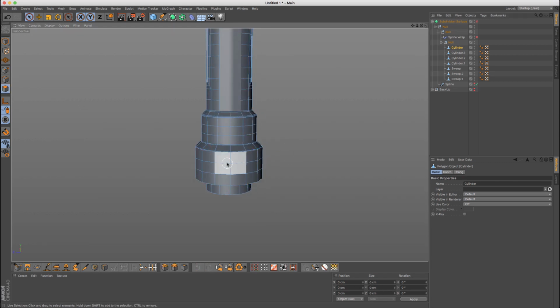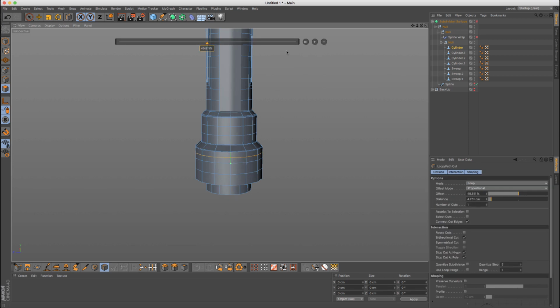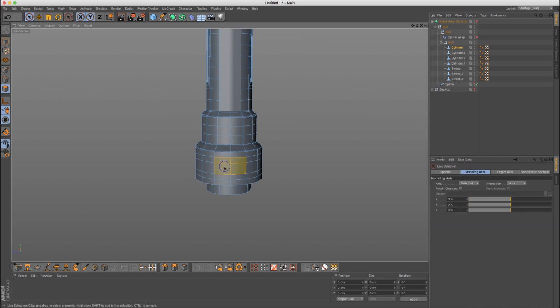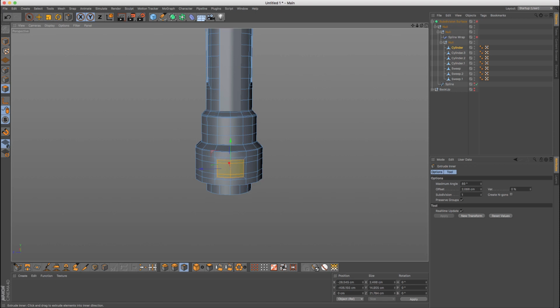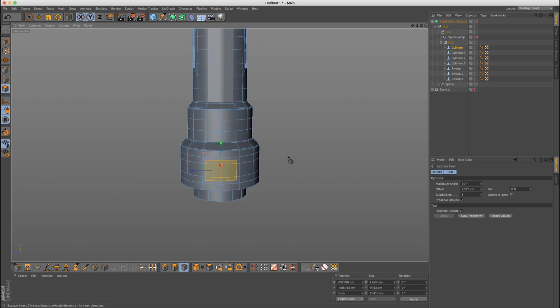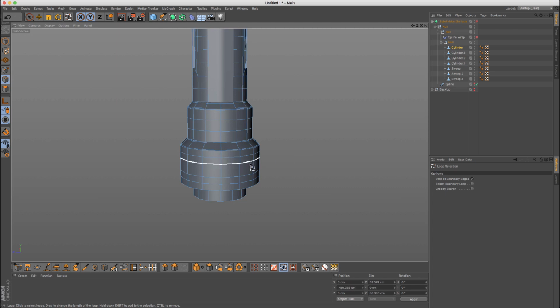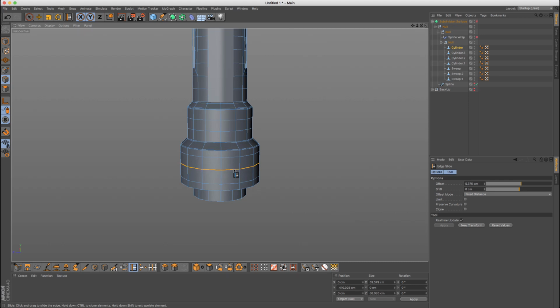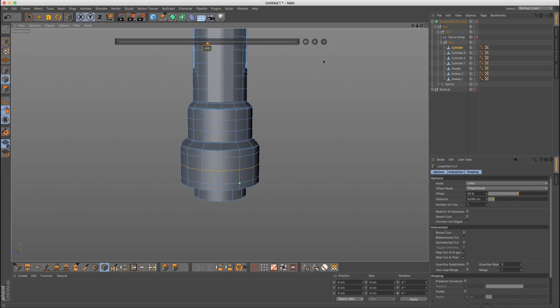And also here, maybe we can add a few extra edge loops, just so we can, let's say, use this area and create sort of a circle or something in the middle. So before we do that, let's just create extrude inner. And actually we don't need that many edges, so let's remove some. So this one can go, and this one we can actually move to the middle, or even remove that one and reposition exactly in the middle like that.